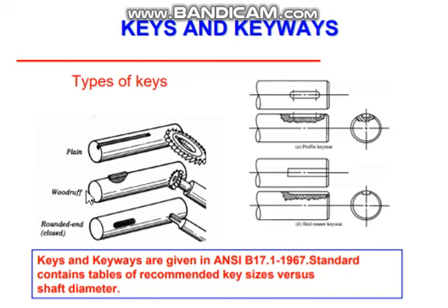In the case of a woodruff key, it is a segment of a disc sort of thing. So you use a milling cutter like this, rounded and closed. You need such a cutter. When you are drawing, you draw the keyways like this. Some standards are given where you can find the keyways in the standards.